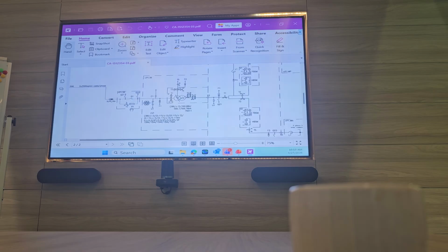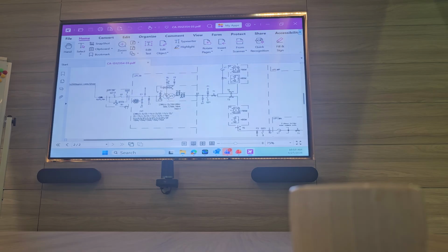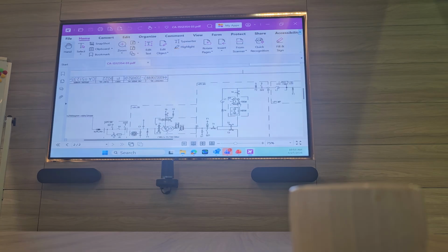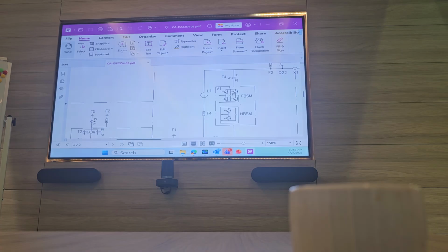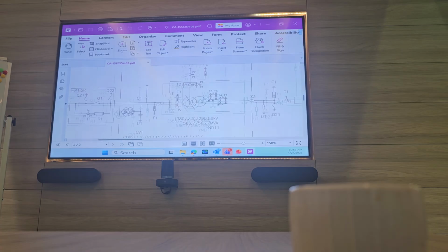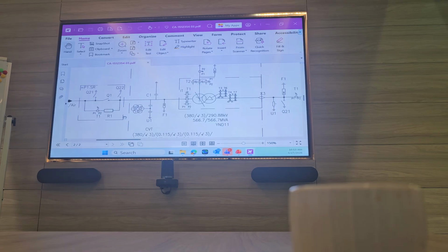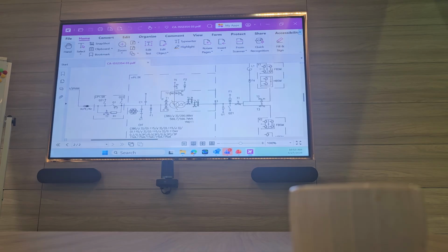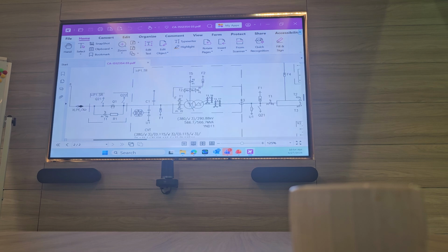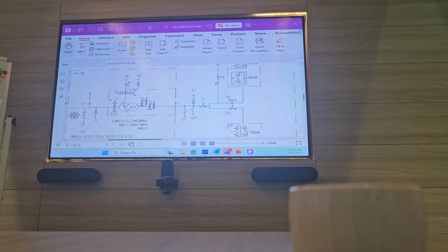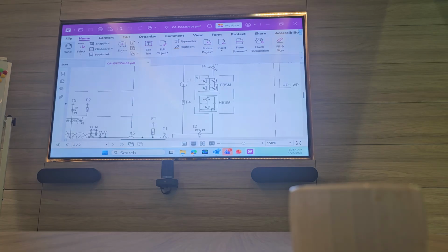Normally this works during energization time only, to charge the DC capacitors. First, these capacitors will be charged through this resistor. Then it will cut off, and the bypass AC circuit breaker will switch on. Yes, we need initially to charge these capacitors to feed voltage to the valves.